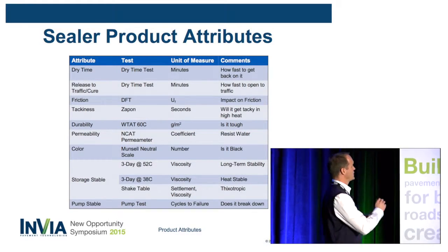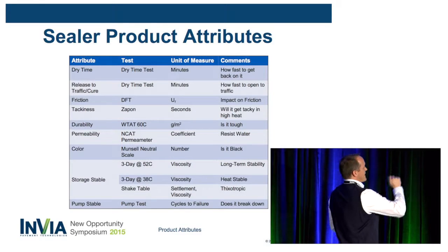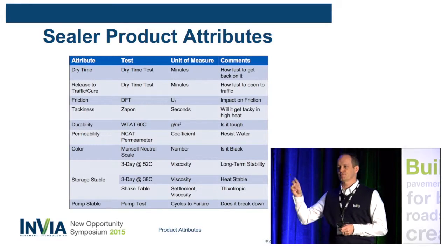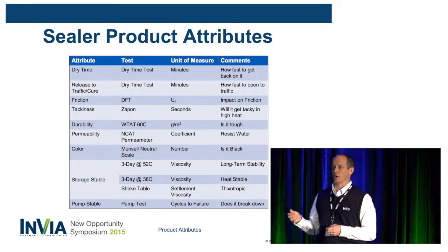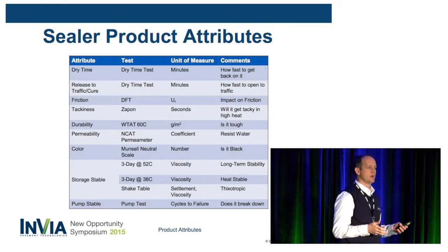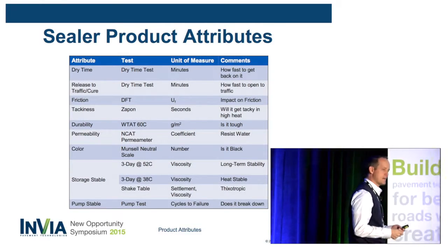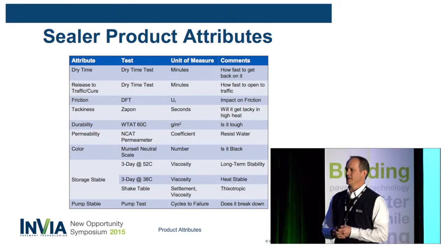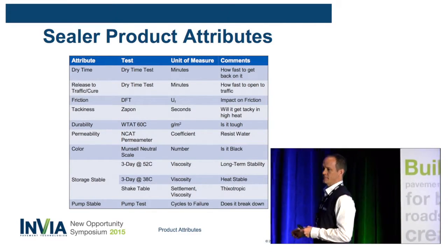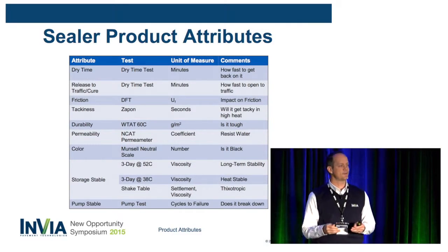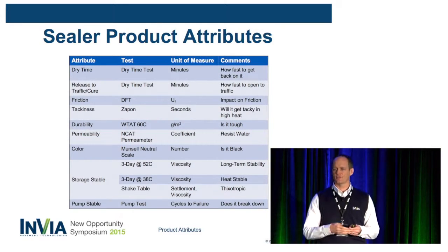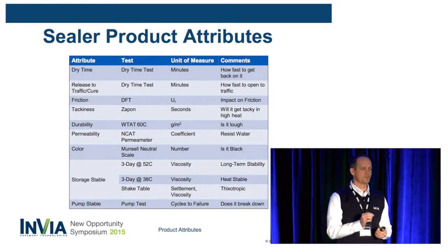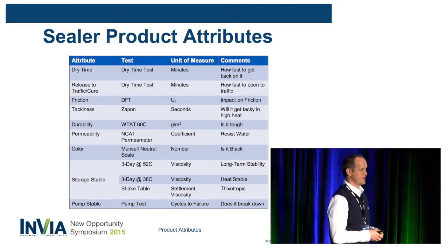In both cases, folks, they both have to do with basically the removal of water from the system, right? And the difference between those two things is the amount of water that has left the system. Dry time is really that moment that you can get on top of that surface and put a second coat down or put the stripes down. It is not cure time. You may not necessarily want to have a pickup truck pull into that parking stall and turn the wheels at 0 speed. The system may not be ready for that torsional abrasion.